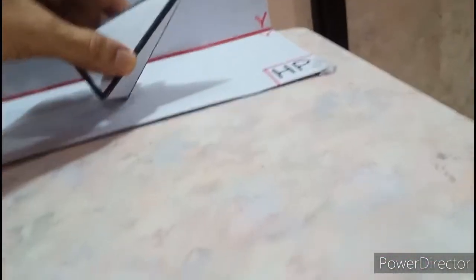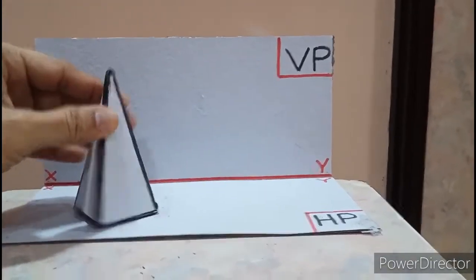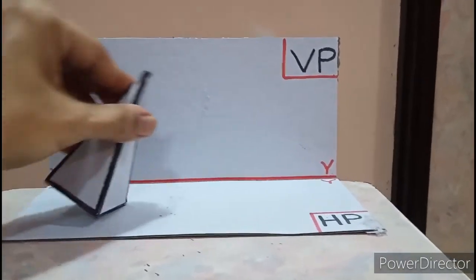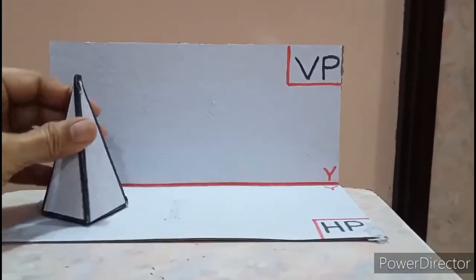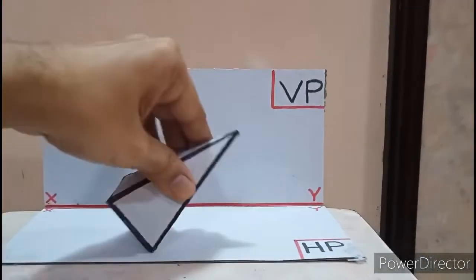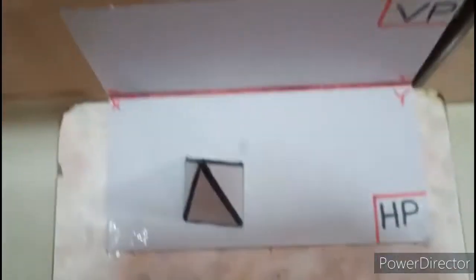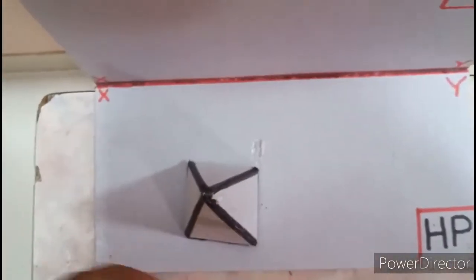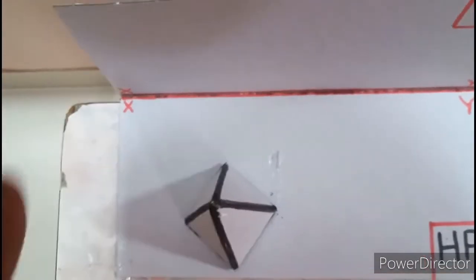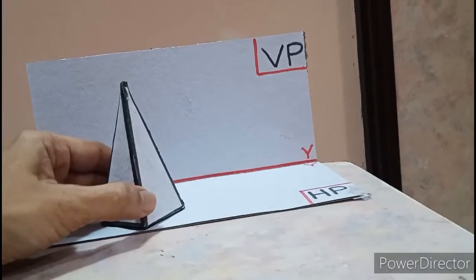So very simple. You just need to hold the pyramid and turn like this. If the right side is a corner, then the corner will rest. Simple. If the right side is a base edge, and when you tilt, the base edge will rest. So for the third diagram, second diagram, first diagram, right side base edge. If the right side is a corner, the first diagram is the top view, the second diagram is the front view, the third diagram is the tilt. So the corner will rest.